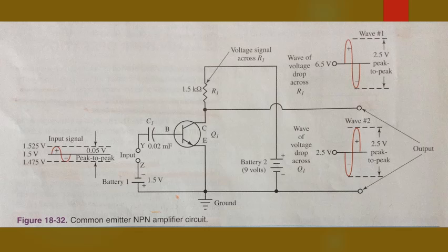The total voltage EB2 is equal to the sum of the voltage drops in that series circuit, including the transistor Q1 and the resistor R1. During the negative half of the input signal, the bias voltage on the base is decreased or lowered. As a result, the resistance of the emitter to collector will increase, causing current to be reduced.